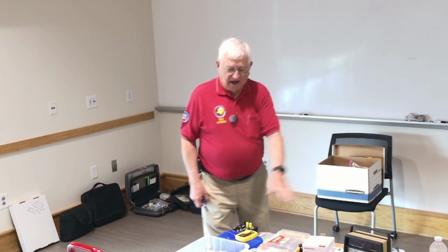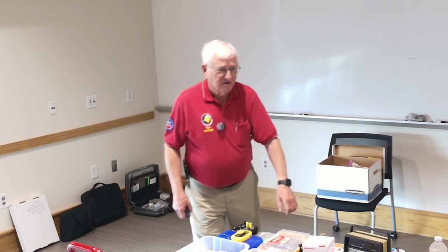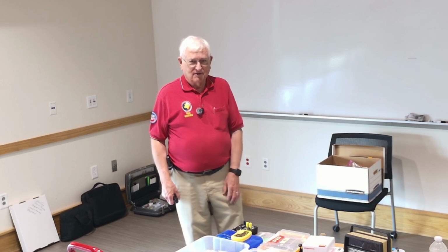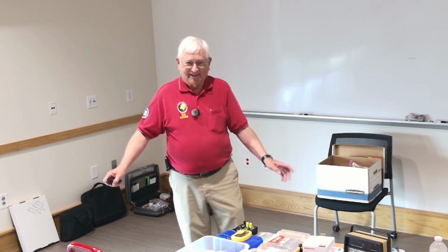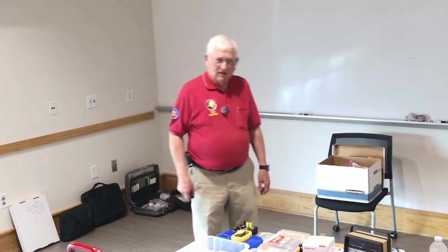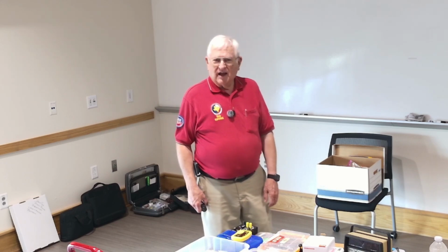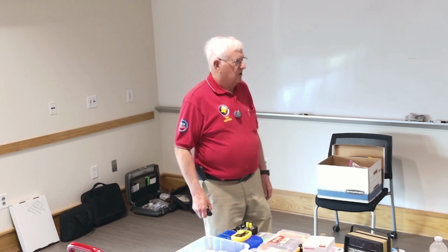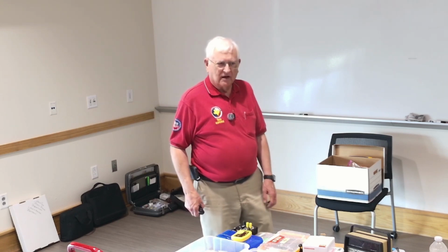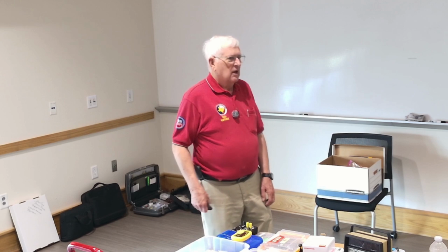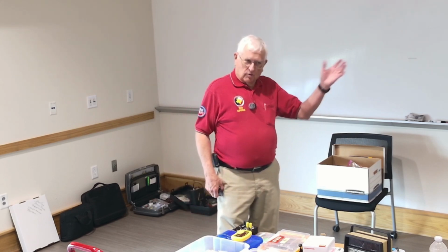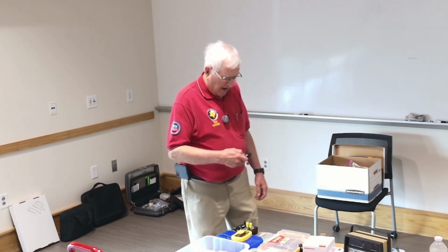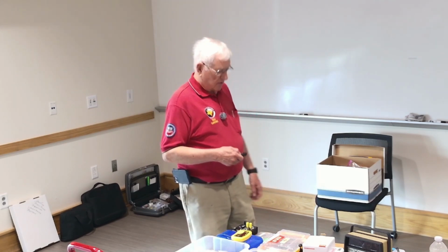This one says the inductance is 170 microhenries. This one says it's 10 microhenries. It's just way out there like that, and that's kind of typical, really. But do you need all of that? No, not really for most things. Now, if you're in a critical situation where you need those critical values, doing repair work or something like that, then it becomes important. In that case, you invest in a really good meter and pay a couple $300 for it, which will give you much better accuracy. We've got several of those. We'll play with those when we come to it.